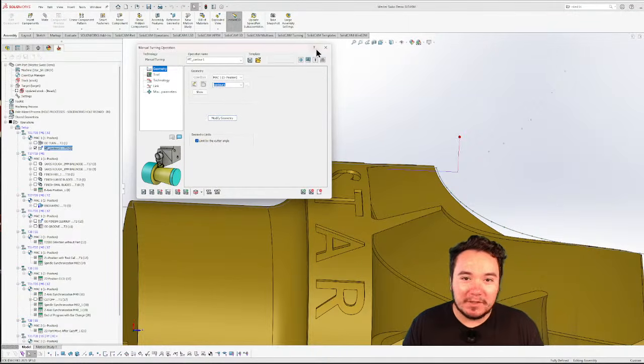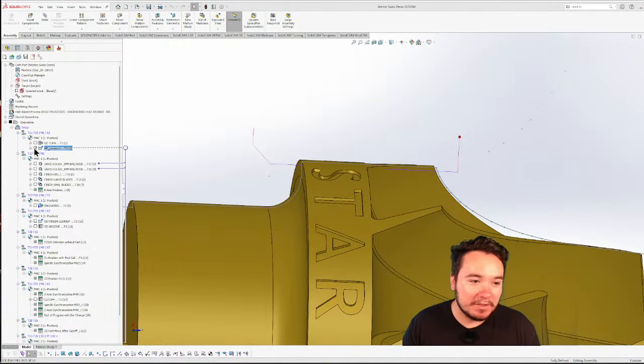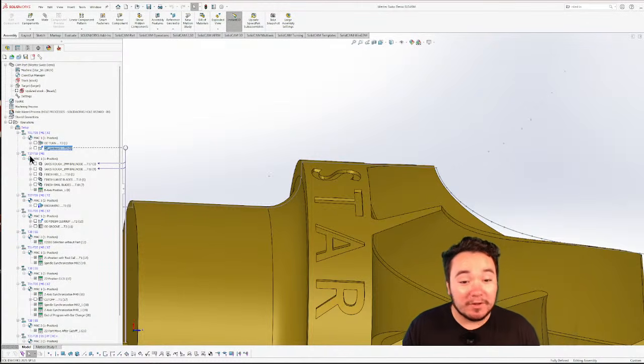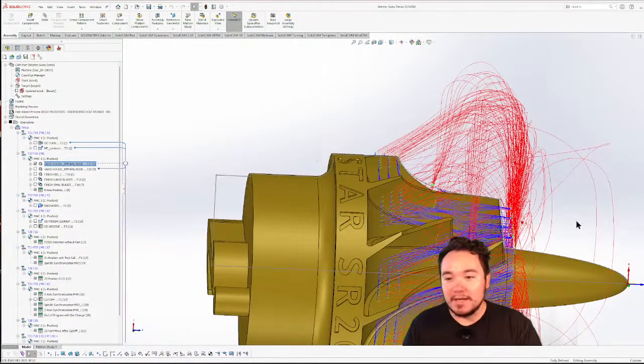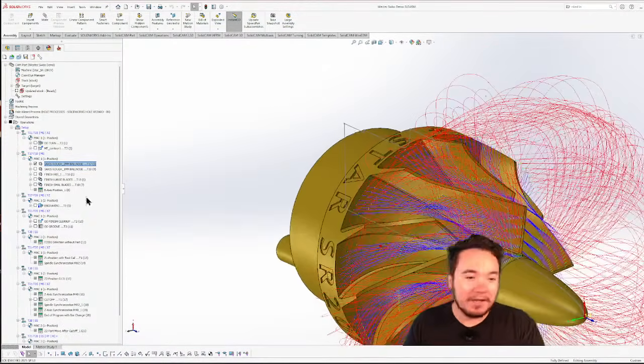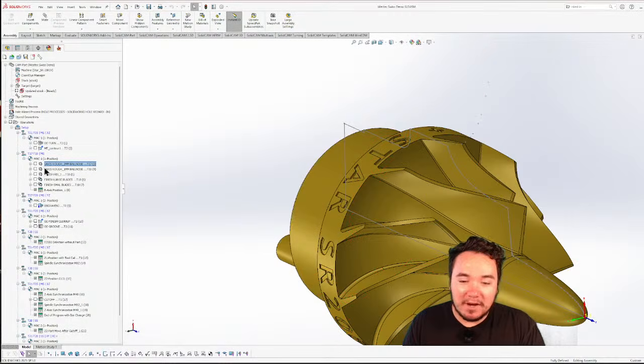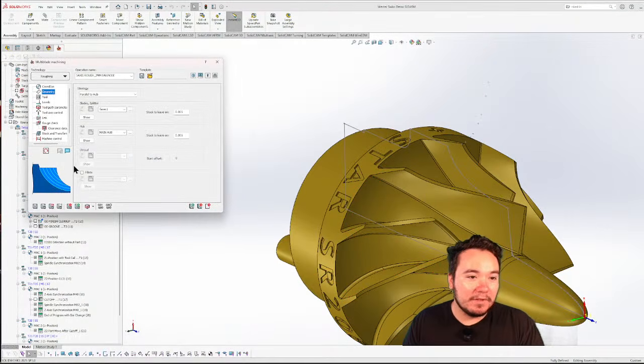And these are pretty simple tool paths. Swiss machining, it's just milling plus turning, or turning plus milling, turning first. Yeah, so let's go to the next operation. So this is when it gets a little hairy. This is the rough that we did with a 2mm ball nose.